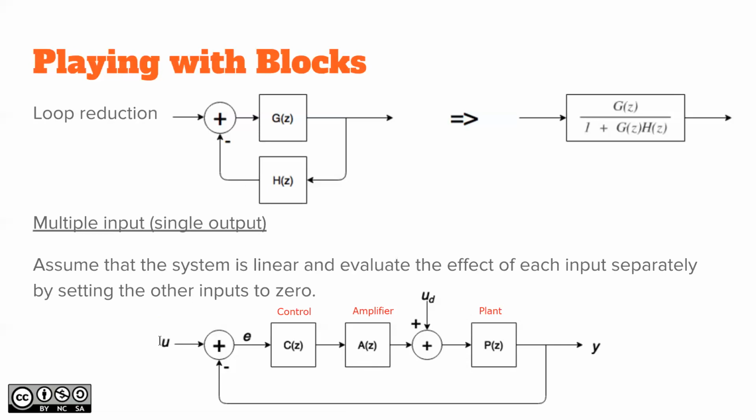This is the value we want to set, the control value, and here is a measurement. For example, if the plant tries to increase the speed up to, say, 1000 RPM, this would be your tachometer signal, and this feedback measures directly whatever we want to control.